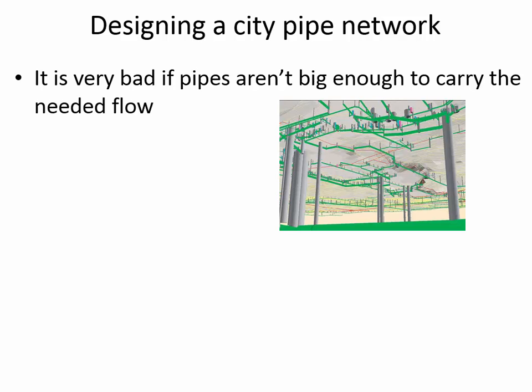then the pressures would be really, really low during the high demand parts of the day. I mean, that's the relationship: if you put in a small pipe, then the pressure goes down as the flow rate increases. Because remember, our relationship that defines the change in pressure is the Darcy-Weisbach equation. The Darcy-Weisbach equation says that head loss due to pipe friction is f L V squared divided by D 2g. Or if we write that in terms of flow rate, f L Q squared divided by D 2g A squared.